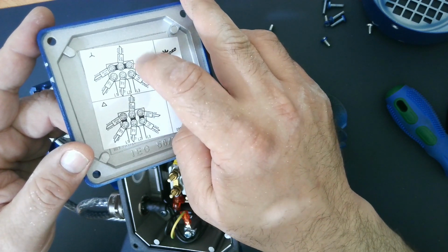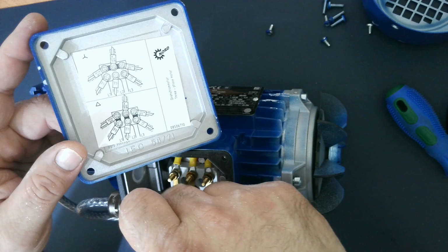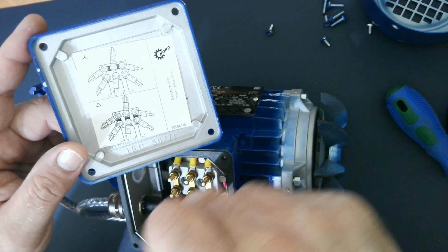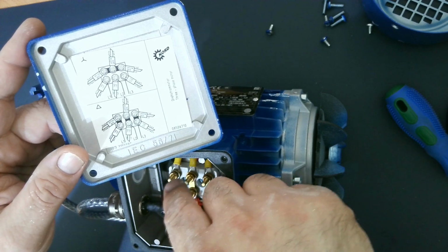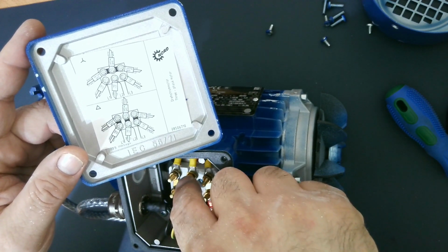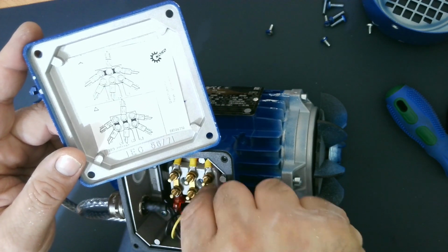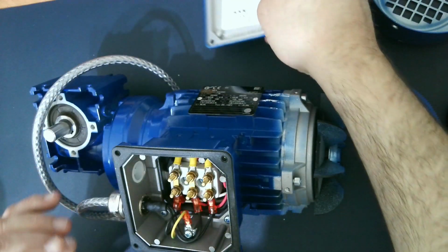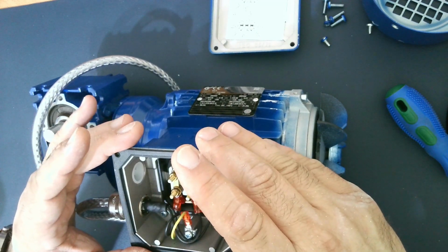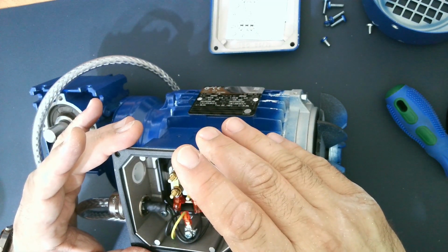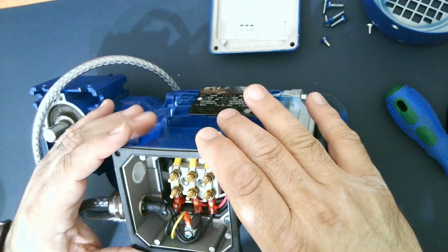That one will be the star connection. If we connect these 3 terminals together and feed the machine from 1, 2, 3 or ABC or UVW, whatever. But if you like to connect the machine as a delta, and now the machine is connected as delta, you are going to connect this winding by this winding, and this one by this one, and this one by this one. And also you feed the machine from these 3 terminals. So it's clear here we have 6 terminals for this machine, but I'm going to look at the nameplate later on and the terminals for the dismantled machine, and we're going to speak about that one in detail.